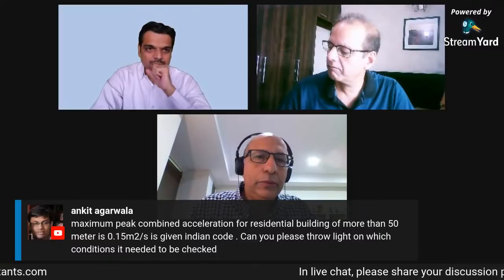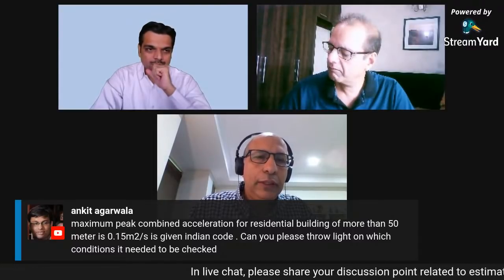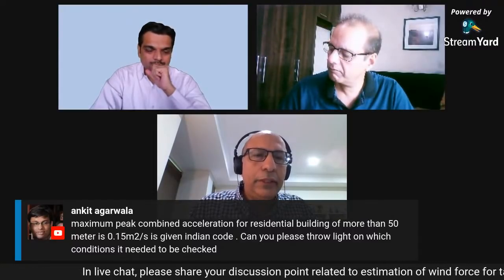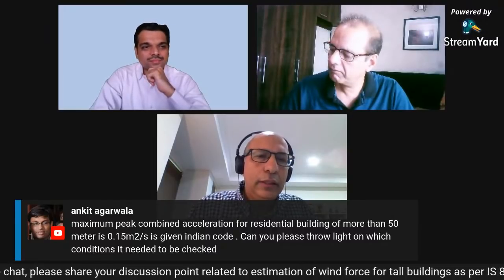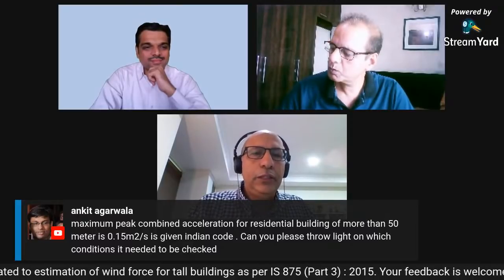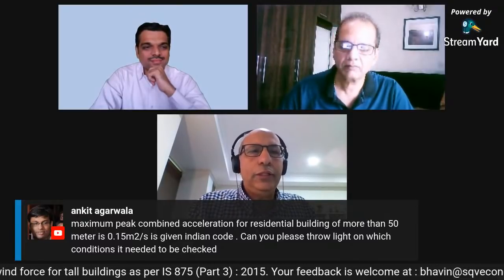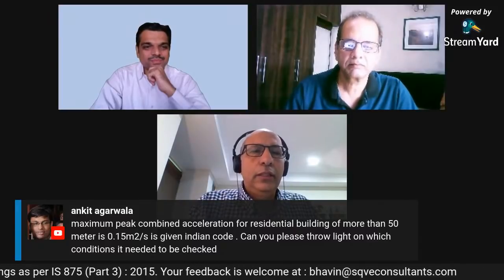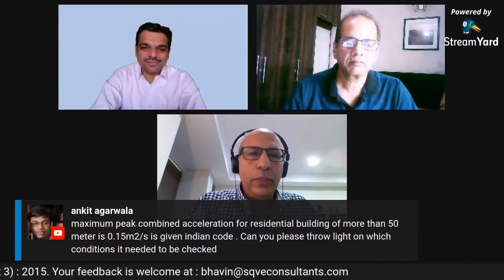As the building becomes more stiff, people can feel the same acceleration in a more heightened way, and that's because our bodies naturally have a natural frequency, and it's very close to 1 hertz, 1 to 2 hertz.